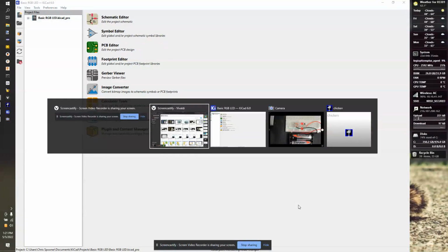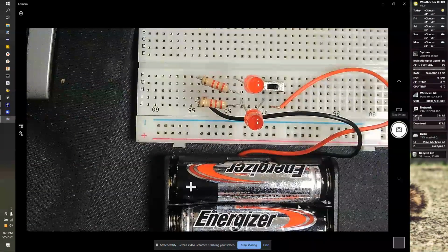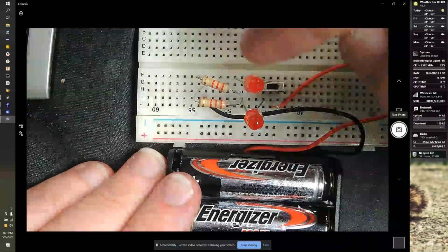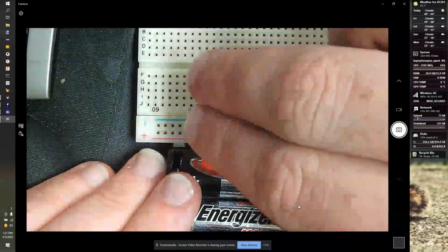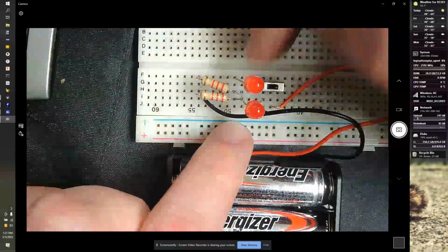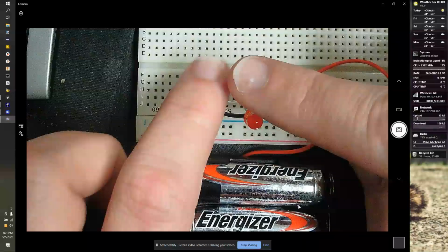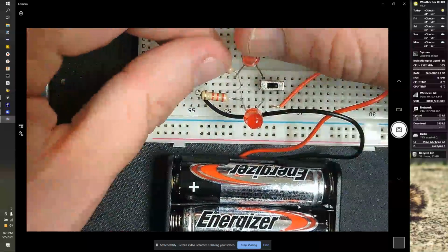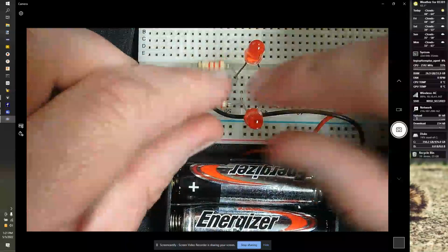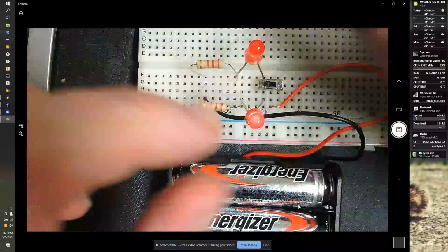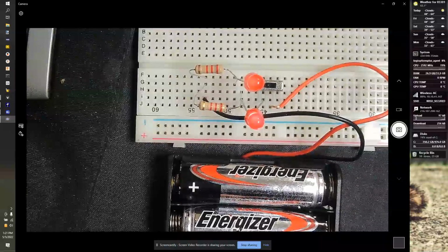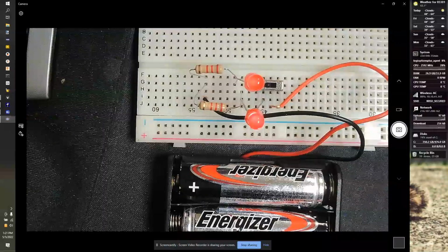In this case, I've built a circuit consisting of a set of AA batteries going into a power switch, then powering two separate LEDs in parallel. So these ends are touching, these ends are touching, these ends are not touching. This resistor and this LED are paired, and this resistor and this LED are paired. I can even move this over one to make it a little more clear. So these two are paired, and these two are paired. So I hit this power, both lights turn on. It's a really simple flashlight, but it will give a sample of how to build something in KiCad.